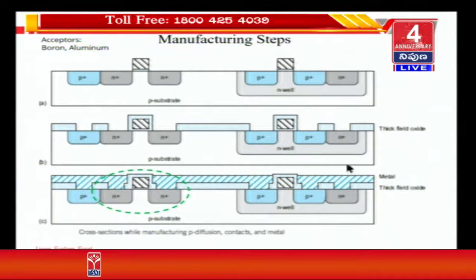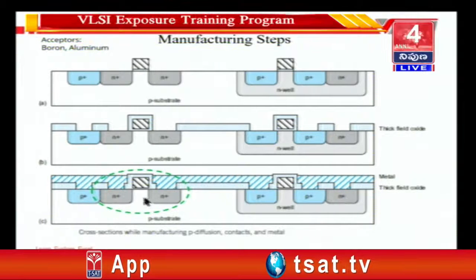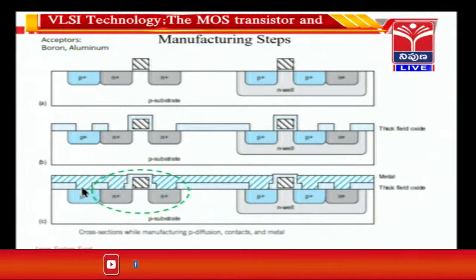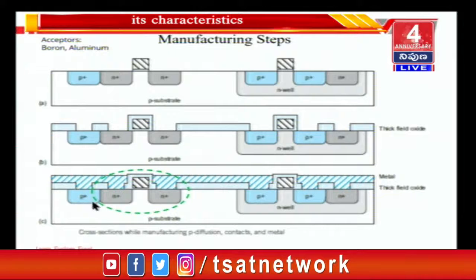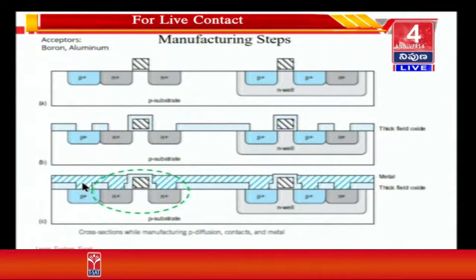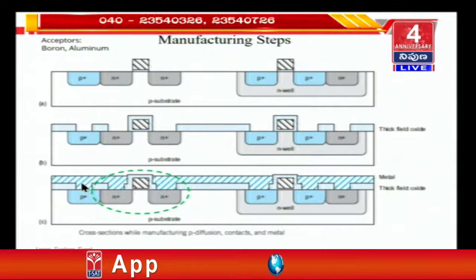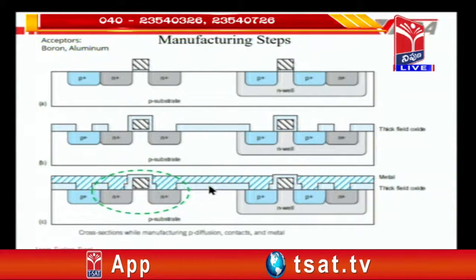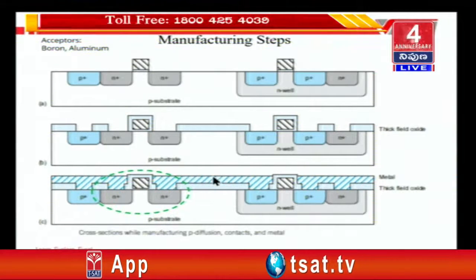So that gives you an ohmic contact at this point with an N plus well over here, and it gives an ohmic contact at this point with a P plus well over here. So these are required to form ohmic contacts, so that this metal contact, this P substrate, is connected to this metal contact through an ohmic junction, not a diodic junction. This is how the two transistors will be fabricated and connected like this.